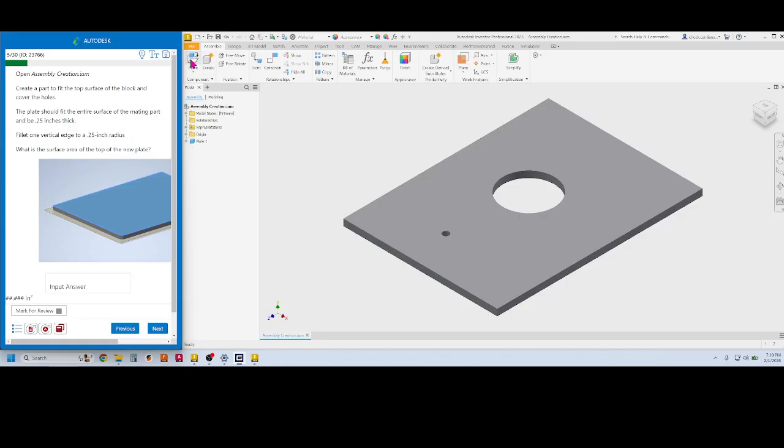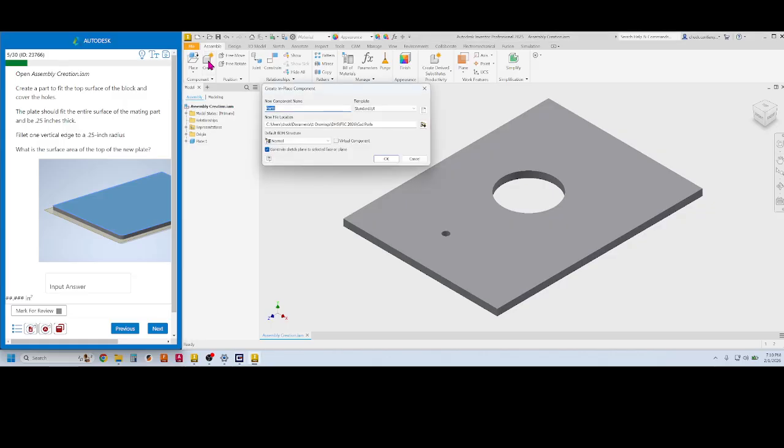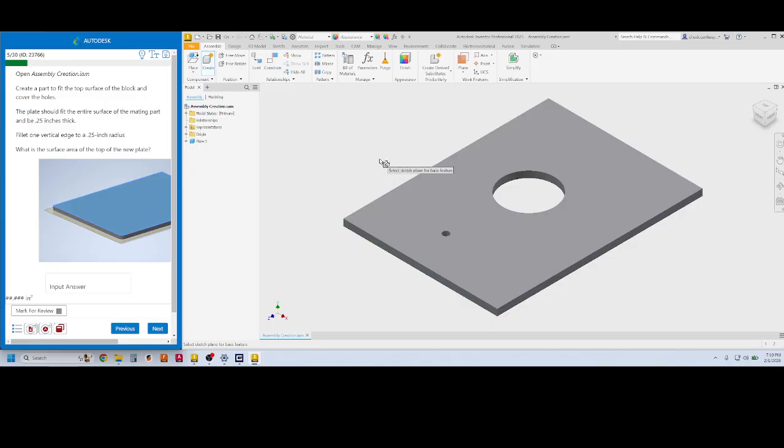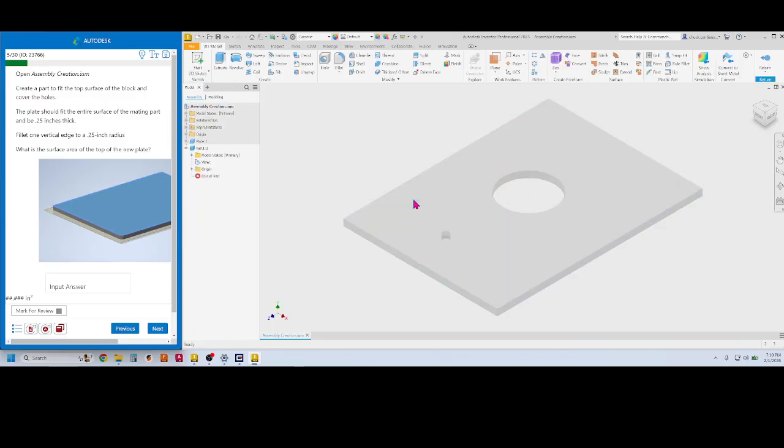So what we'll do there, we're creating a new part. We've got plate. We're going to create a new part. Create is up here. Click Create. Part 1 in this instance. This rare instance is okay here because we're not saving it. You say okay. It wants a sketch plane for base features, so we click on that. And now we're editing part 1 inside of the assembly.